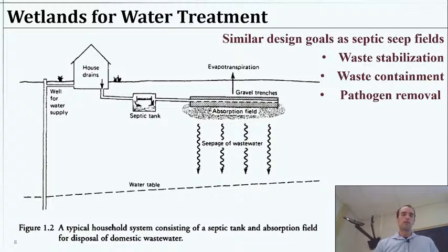And so instead of having a system like this, the question becomes, can we just directly send this into an engineered wetland where it's kind of constrained so that it can have the time to assimilate all those nutrients and the carbon, the oxygen demand, in a way where it's not just going to kill all the organisms, in a way that we can keep that in the same sort of area.